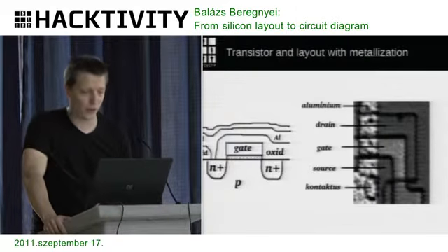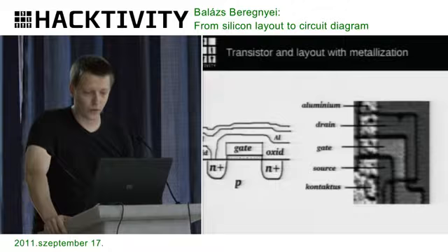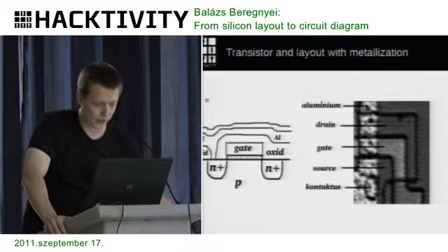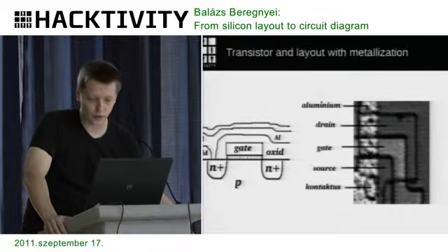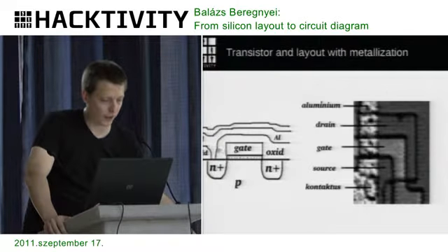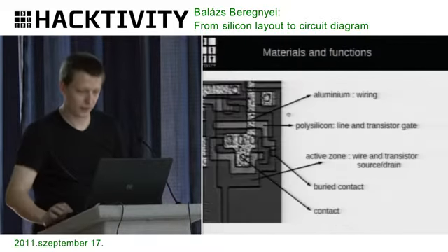In this processor, there's only one metal layer. And since aluminium is on top of the structure, it can be laid over a transistor without tampering. And if you need to connect it to the transistor, then you do this, connect aluminium to the N plus zone.